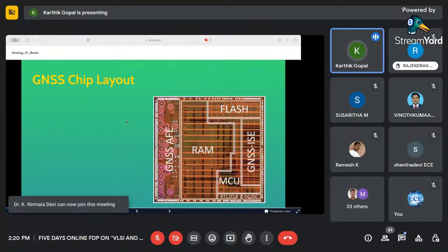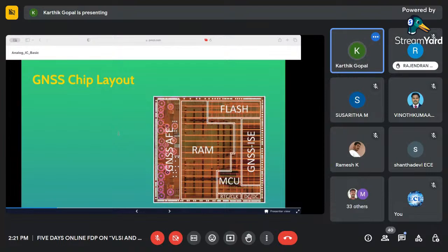But in ICs we implement the inductor inside. Have you ever come across crosstalk? Let's say two systems are working in the same frequency, so you are not able to receive that signal. Let's say I'm talking in some frequency, and there is the same frequency with noise outside. You may not be able to hear my voice. That is the problem when you have multiple frequencies in a chip. Each inductor talks to each other. So that is a very difficult and complex part while integrating all the inductors in a chip.